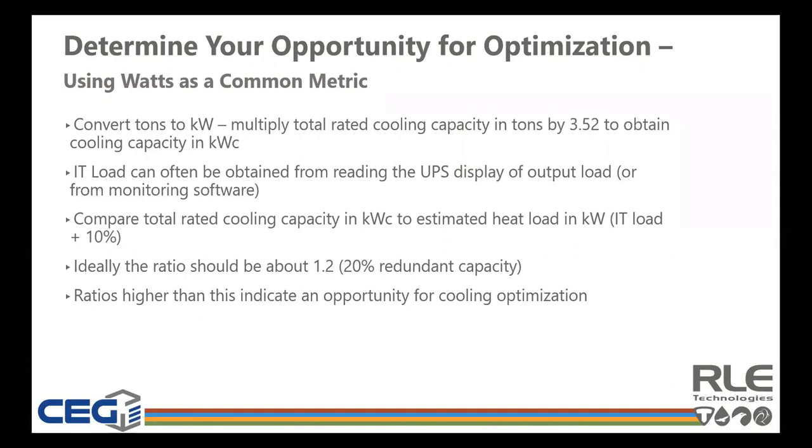The next bullet is about capturing your IT load. There are a bunch of different ways to go about doing it. I have one here, reading the output capacity of your UPS. That can be done at the UPS user interfaces, through monitoring software that comes with your UPS, and sometimes even from any type of monitoring associated with an RPP, if you're using those to distribute power into your aisles, as well as from floor-standing PDUs.